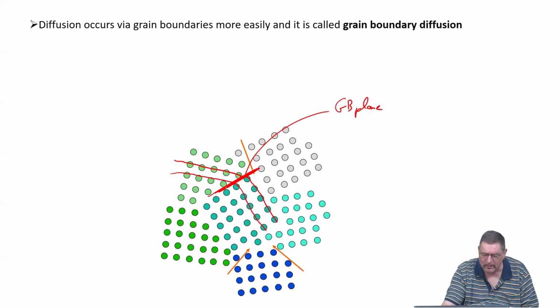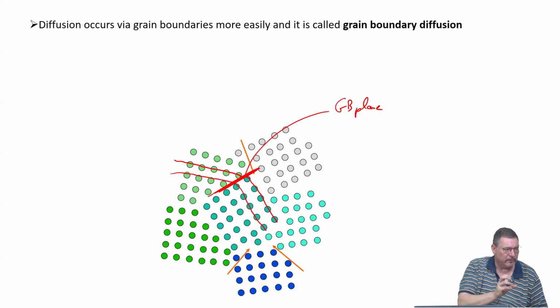So there's a one-to-one connection between the lattice planes. And this is the situation where we have a specific CSL type lattice, so coincident site lattice of high symmetry, let's say. So you have many of the atomic positions in the grain boundary plane occupied by atoms that fit to both lattices.